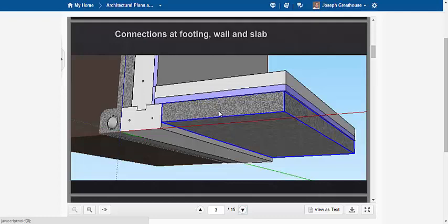So like what you see on gravel roads is what we put down here. We compact that the best we could. And then this next blue layer is insulation. Now, either before or after that layer of insulation, we should put in what's called a vapor barrier.